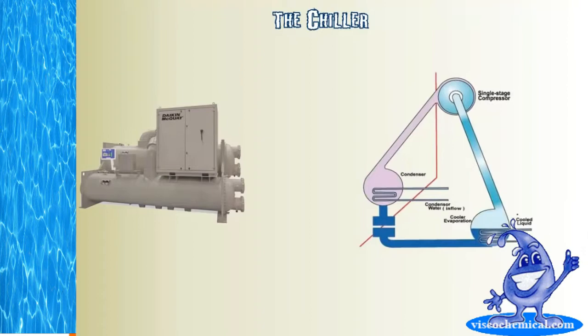One other thing to note about chillers is that in these barrels that you see here, there's many different bolts that come across here that seal up the 2 ends of this barrel. Inside the main portion of this barrel, these water lines that you see here are actually long tubes that run the full length of the barrels. So if you ever hear somebody saying they were changing out tubes or they have dead tubes in the barrels and so forth, these are the tubes, and there's many of them. I've seen some chiller barrels that had literally 100 or more inside the chiller barrel. So there's tiny little tubes all throughout this chiller barrel, and that's where you get the water running back and forth through this barrel to do the heat transfer.